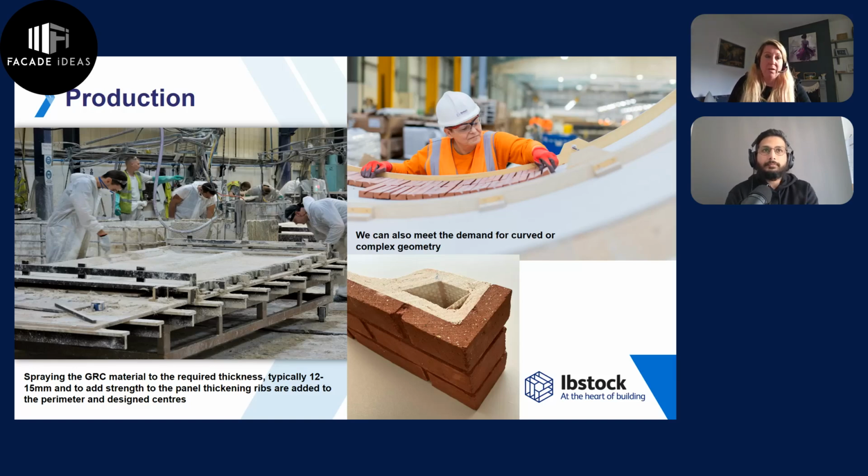Yeah, exactly. So as Josefa says, there are what we call thickening ribs to the edge of this panel. So you can see it being sprayed on. It's sprayed over either the mold if it's plain faced, or if it's brick faced, over those brick slips. And we create those thickening ribs. And where they are located is typically around the perimeter of each of the panels, but also where we designed and calculated the requirements are. You just see in the top there where we've got a photograph of where someone is using the brick slips or placing them into a curved component, and it's an excellent product for more curved or complex geometry, for providing the aesthetic that the architect is looking for.